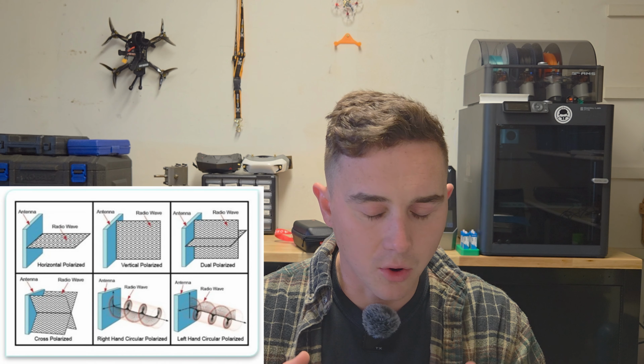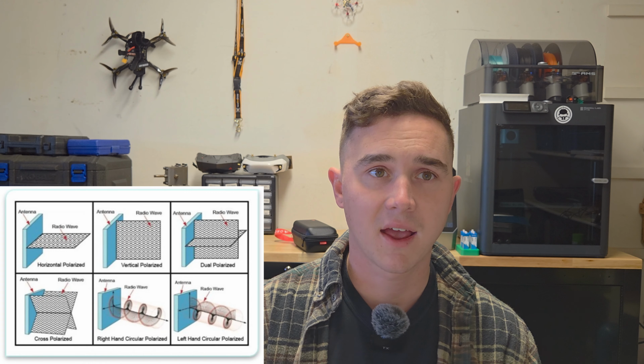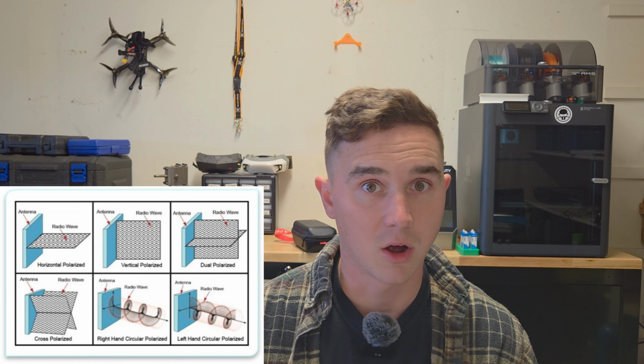Okay, so if I have a left hand circular polarized antenna on my goggles and I have a right hand circular polarized antenna on my video transmission system, I'm probably still going to receive that transmission for a while until I reach a certain range and there's loss. Okay, so the reason why we do this is so that it interferes less with other systems. Okay, you have a linear antenna on a video transmit system, it happens on whoops a lot. But most commonly, you're going to see right hand circular polarized or left hand circular polarized.